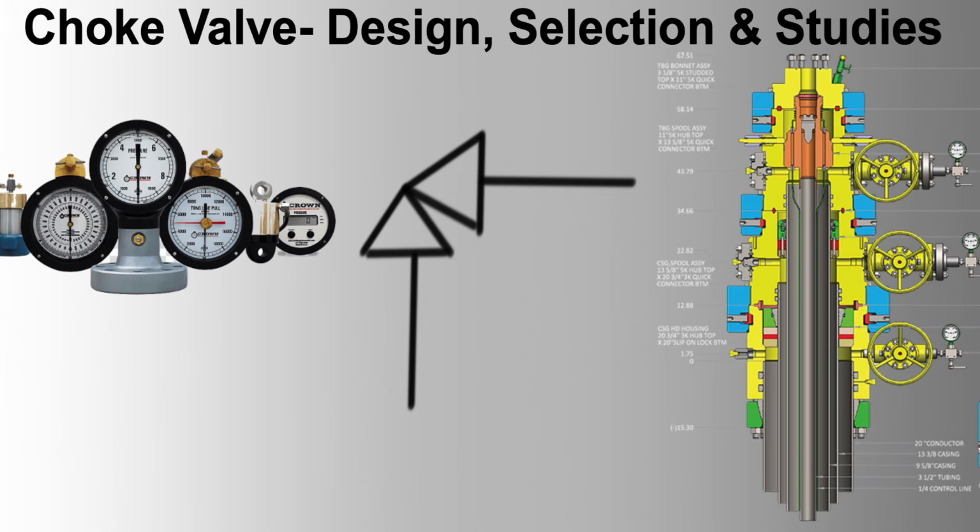2. Corrosion in sour service. Problem: corrosion of valve components in H2S environments. Solution: use corrosion-resistant materials like Inconel or Hastelloy for body and trim. Ensure compliance with NACE MR0175/ISO 15156 standards.